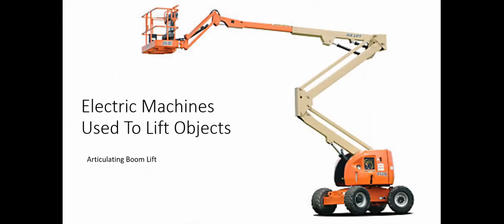And I'll go next, and I'm going to talk about the articulating boom lift. The boom lift is made up of all these different kinds of arms, and it's made to get into some tight spaces. This little section here on top acts kind of like the scissor lift, and it just goes up and down. And then this arm here can swing at an angle, and then right here it extends out or booms out.